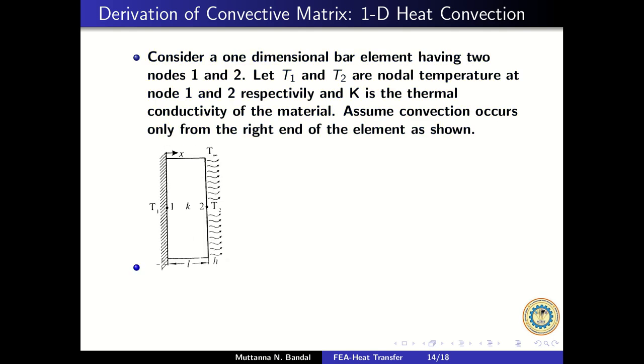For that I have given an example here. One end of the surface is subjected to a temperature T1, the other end is subjected to a temperature T2, and there is a property K here, which is the thermal conductivity. For that we have already derived the equation. Now there is a temperature T infinity, which is the air, and this will be a convective heat transfer. So I cannot apply the conduction law here. I have to apply the convection law here. The same is explained here at the top. You can read it out.